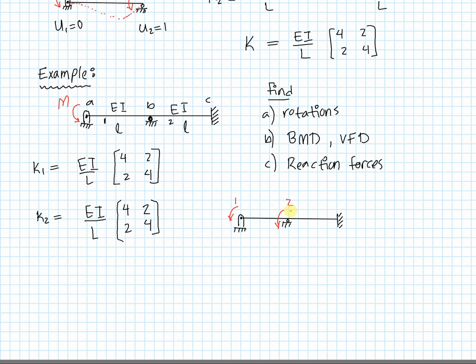One thing that I'd like to highlight is that yes, you may be thinking that a roller can move in the horizontal direction, but because this is an introductory course and horizontal motion in a beam like this involves axial deformations, I'm going to be ignoring axial deformations just because this is an introductory course. And axial deformations tend to be small when you compare them to flexural deformations and rotations. Usually they end up in the order of 1/100th of all those other deformations. So I'm going to ignore those for the sake of this course.